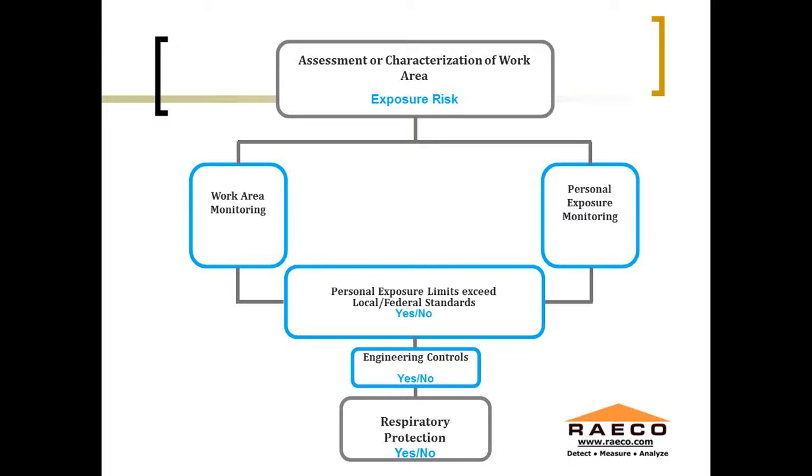And that would be typically 24-hour monitoring, maybe for a few days or a week, to get a comprehensive look at what's actually going on in that area. And then the other one is personal exposure monitoring. This is where you're going to use either something like a real-time photometer, the size of a sampling pump, to get some basic information on what kind of exposure you might be seeing, to traditional gravimetric sampling with the 37-millimeter cassette.